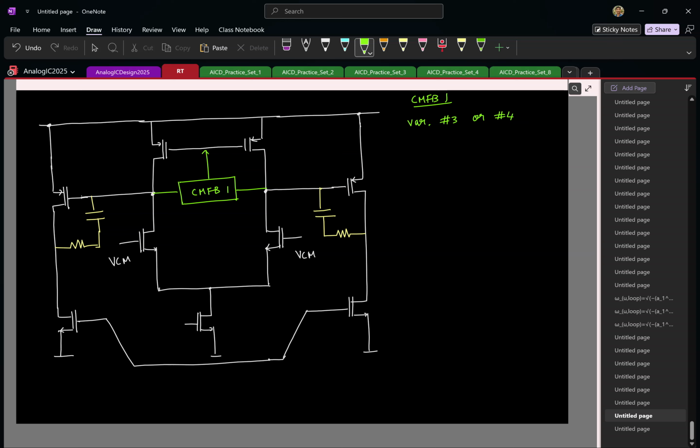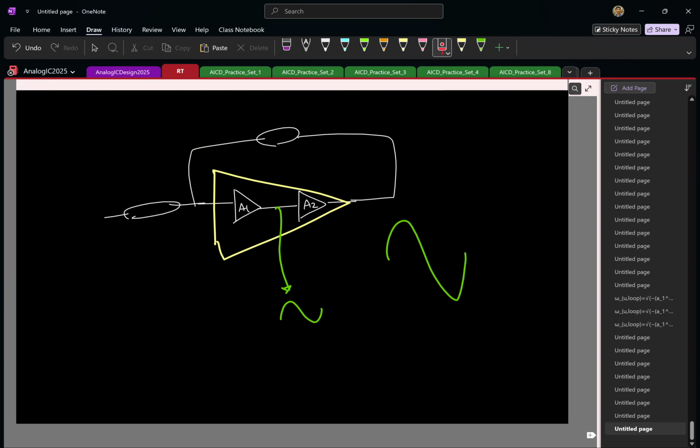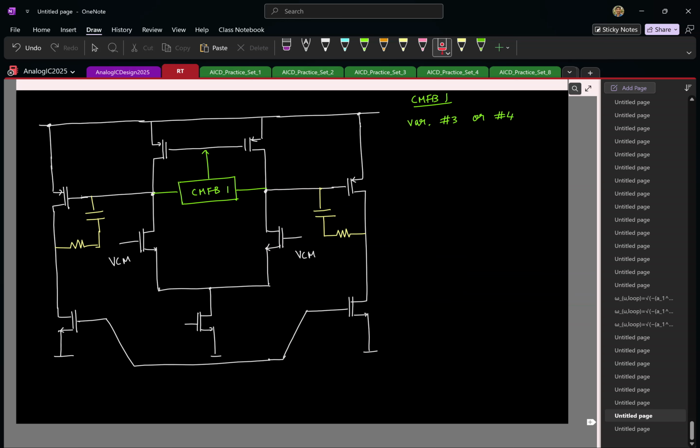Is the reason clear? Because I can't connect the resistor directly because the output resistance of the first stage might be really large, because that gives the maximum gain. So which means if you cannot have a common mode resistor that is much larger than the output resistor, you'll have to use MOSFET based CMFB. But there the swings are a problem. But as we saw now in a 2-stage OTA, maximum swing is at the output. But at the output of the first stage, the swings will be smaller by a factor equal to the gain of the second stage. So which means you can nicely use MOSFET based CMFB. Of course, remember you have to feed in a reference for this. So I'll say VCM ref 1.